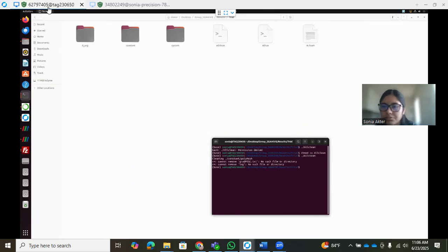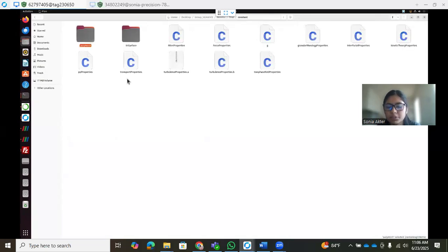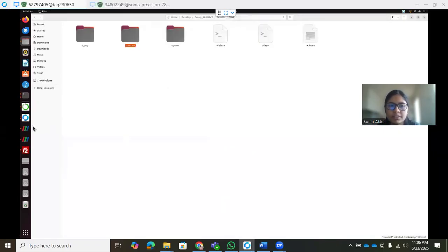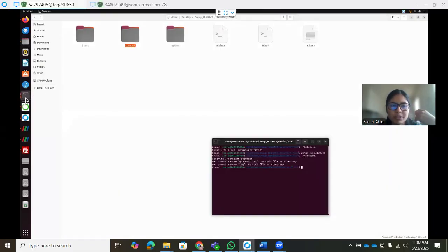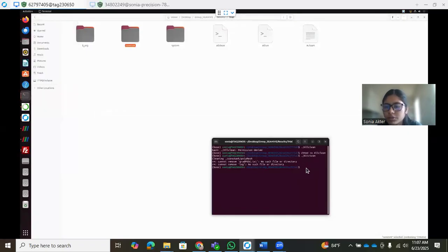So previously we had a zero folder and processor folders, and if you go to the constant folder, it has the polyMesh folder, but it doesn't contain any other files. So when you are using the all clean script, it will automatically delete all the steps that you applied to run this case. In a similar way, we can use the all run command line, which will apply all those command lines to this folder and run it.